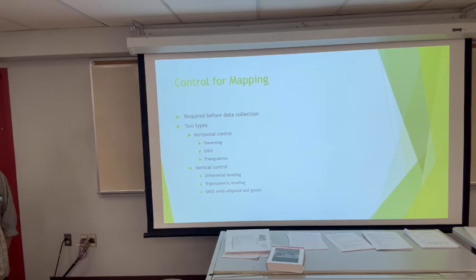A lot of times when surveyors go out and set control, the control points are both horizontal and vertical. However, that doesn't absolutely have to be the case. You can have separate individual control points that have only horizontal or vertical position associated with it. If you have a point that has only vertical control on it, we usually call that a benchmark.